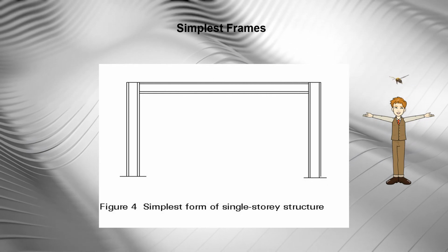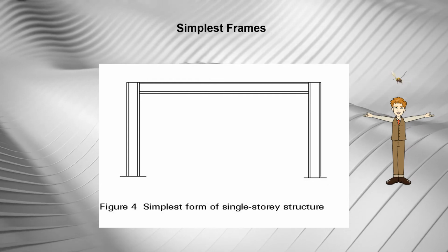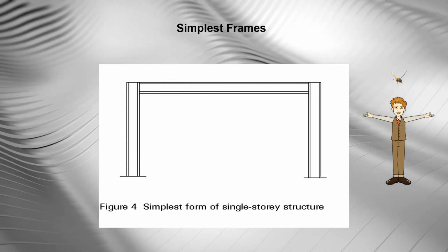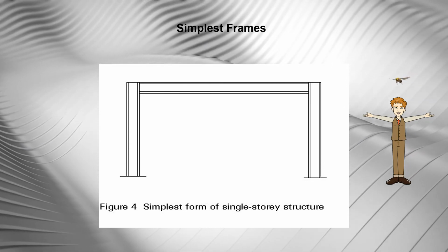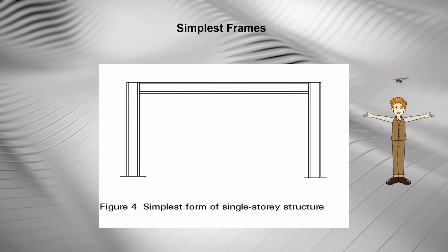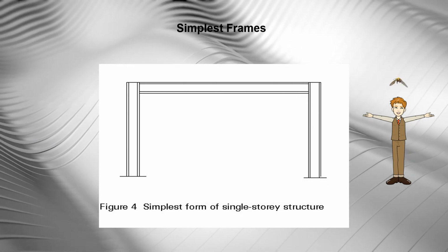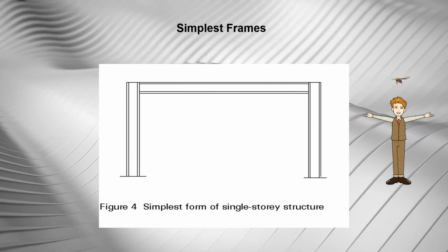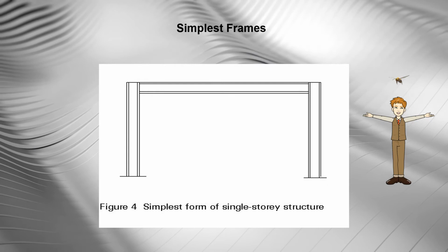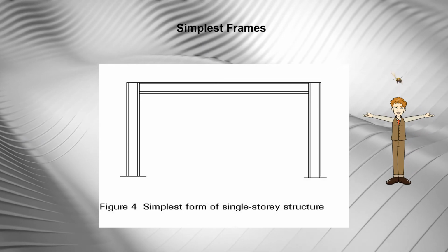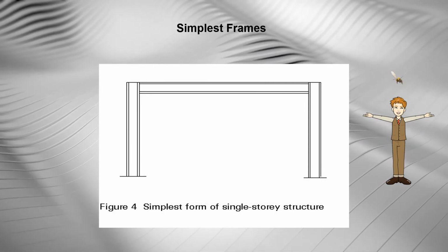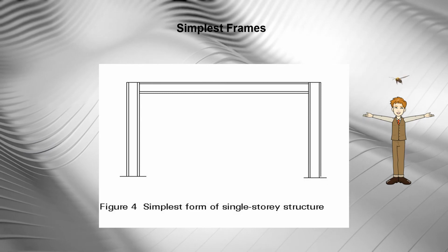Buildings which employ beam and column construction often have brickwork cladding in the vertical plane. With careful detailing, the brickwork can be designed to provide the vertical sway bracing, acting in a similar manner to the shear walls of a multi-story building. Resistance to lateral loading can also be achieved either by the use of rigid connection at the column beam joint or by designing the column as a fixed base cantilever. Rigid connection and rigid column foundation joints also reduce the deflection of the beam and need less weight of structural steel for the frame.